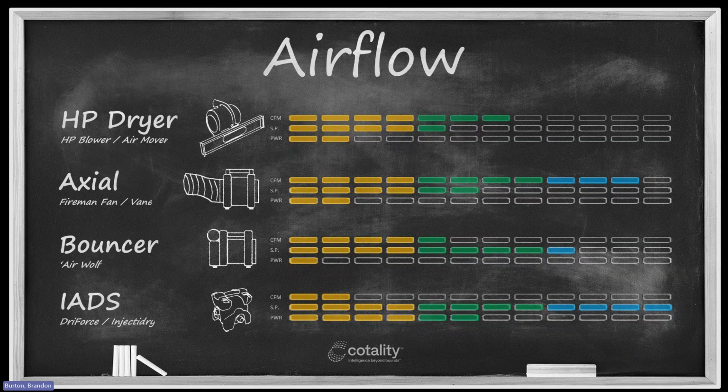Now, at 7 inches of static, what I inflate you can stand on, imagine what I can do with 50. Okay, and just kind of let that sink in for a second. These are designed specifically to ensure that the amount of air that they do produce, which isn't a lot, is going to move, right? If there is any opening whatsoever that is larger than the molecules that make up air, air is going to move through that opening.